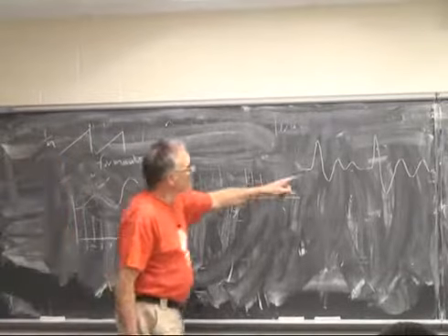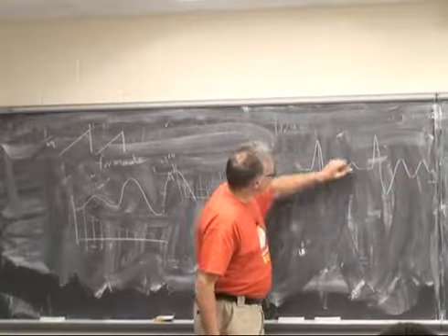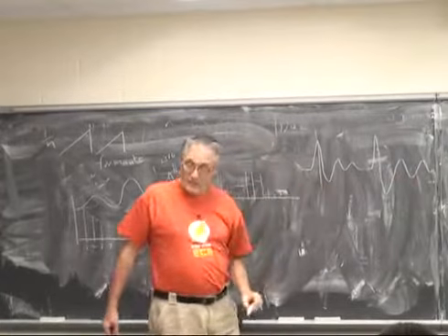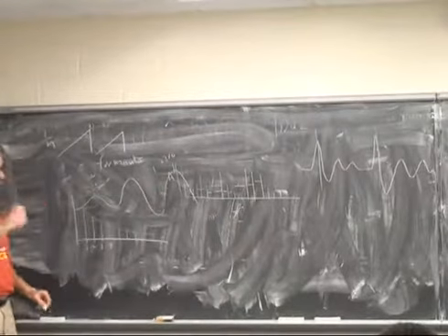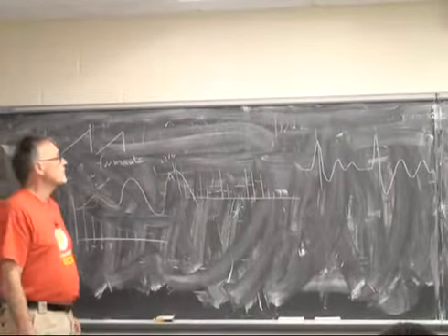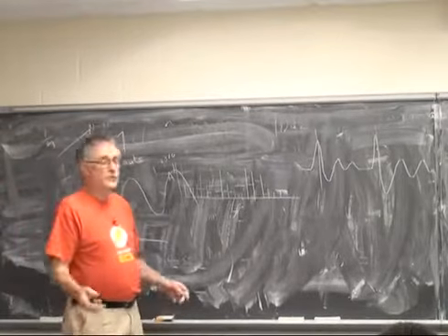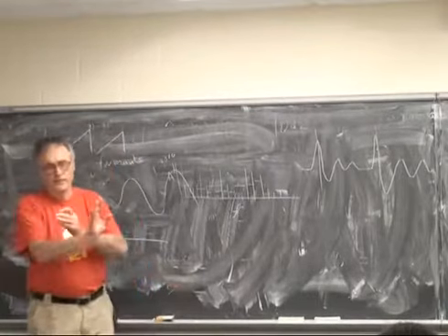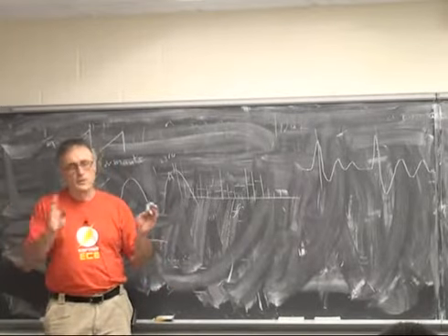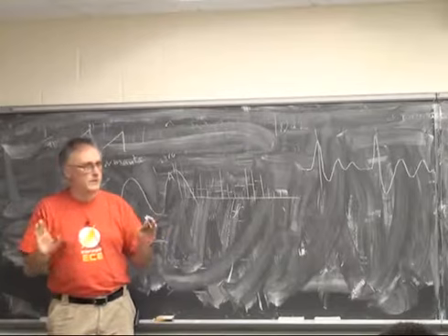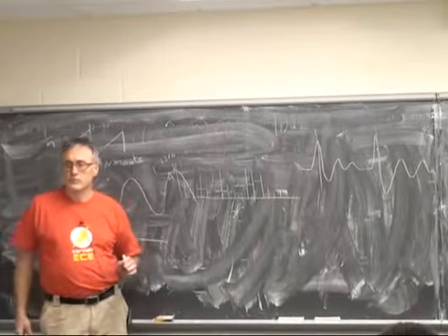So if you can find a pattern in the time domain that looks like this and go from large peak to large peak, that's the fundamental frequency. So some sort of autocorrelation scheme looking for peaks in the autocorrelation may be the best way to get the pitch.